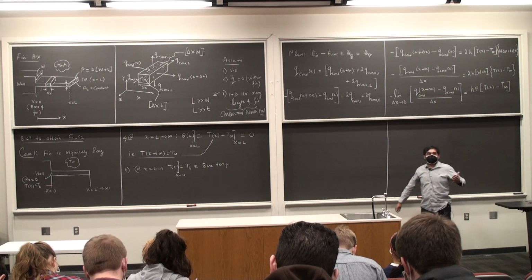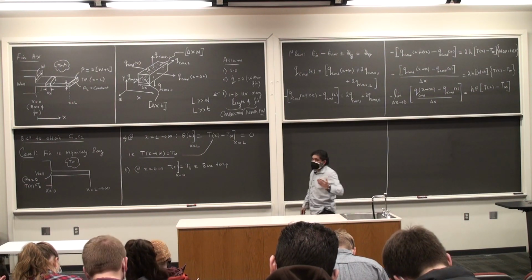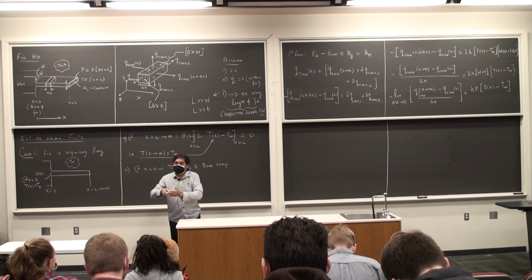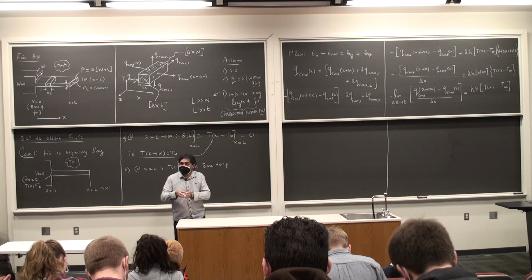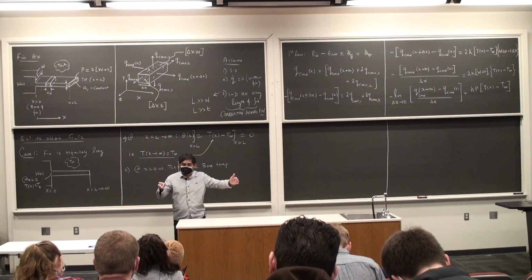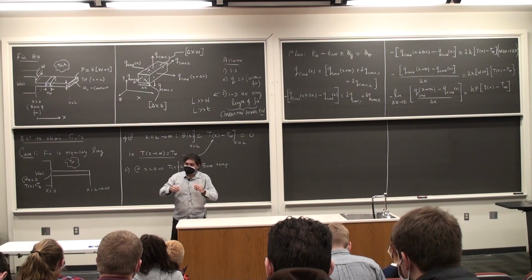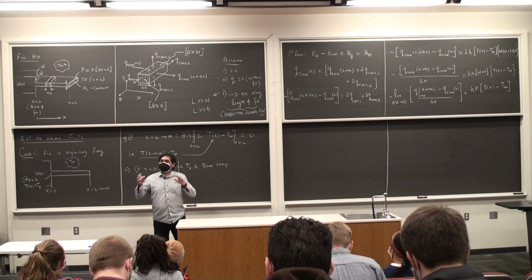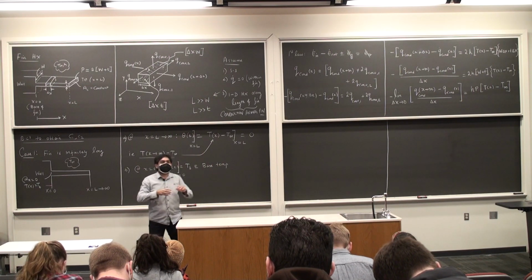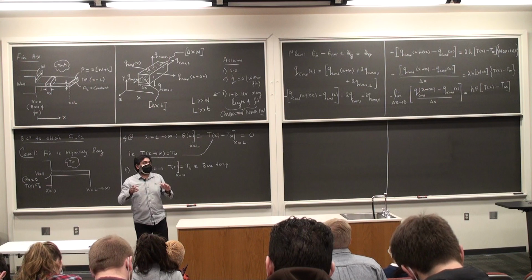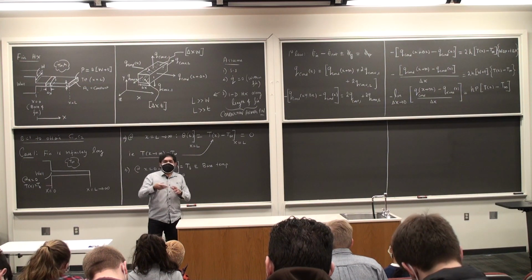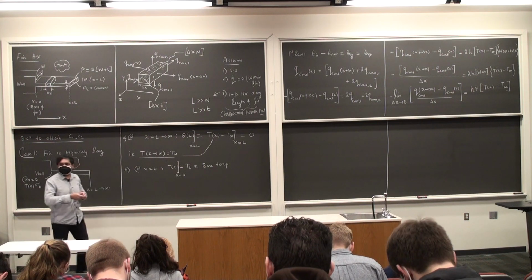If I look at the temperature distribution along the length of the fin, and if the fin is infinitely long, what type of distribution do you think the fin should be having, the temperature distribution? Once again, I have an infinitely long fin, infinite in quotes. I'm trying to sketch the temperature profile along the length of the fin without even solving for these C1s and C2s. What do you think is going to be the general nature of this temperature profile? Exponential decay. There is nothing else to it.